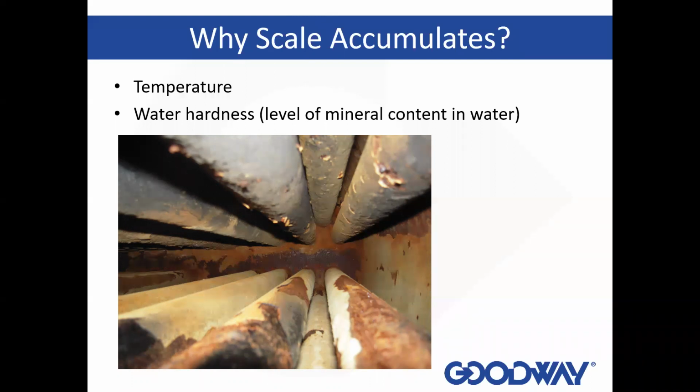it's not like putting sugar into water, where the more sugar you put into it, the more dissolvable it is. In this case, this wants to fall out and leave a very adherent, tenacious scale on the inside of the boiler. Not only with that, as you can see in the picture, you see a lot of brownish orange looking material. Those are corrosion byproducts that are happening in the boiler, because you have oxygen intrusion that's in the water that's coming in. You have a lot of heat and the oxygen can cause pitting effects in the boiler itself.